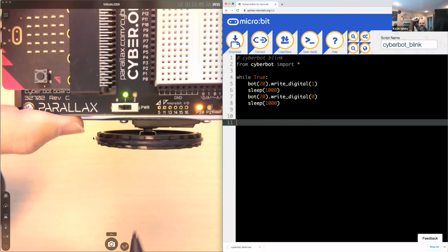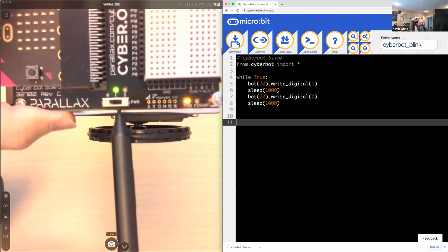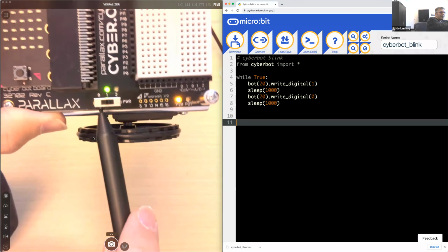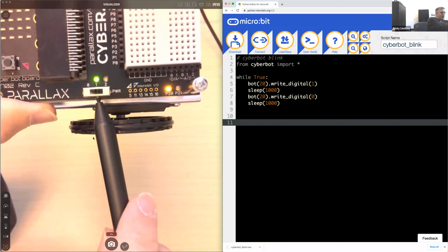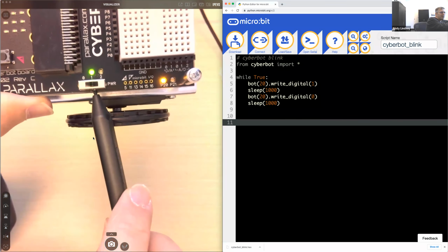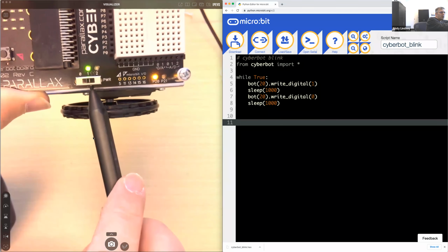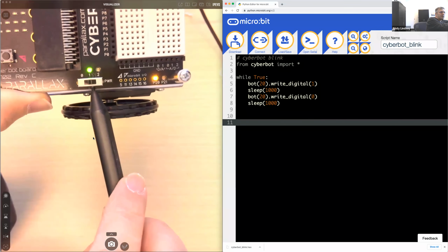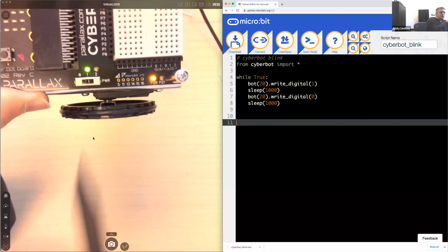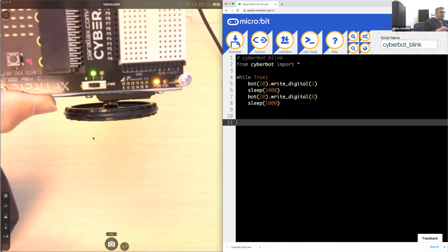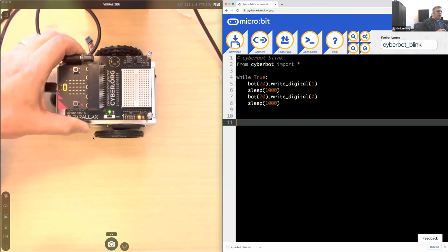That's genius, by the way. I like that. Yeah, we came up with that pretty early on with the Bobot robot back in the early 2000s, maybe 2000, 2001. So position 1 powers everything except the servos, and then position 2 powers everything and the servos. And so you can set it in position 1 to load code.